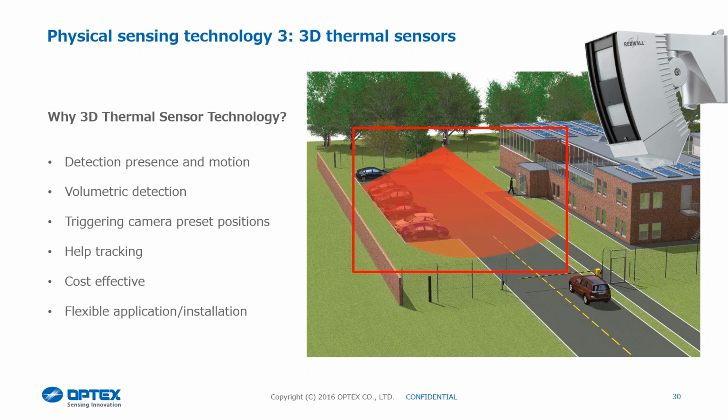Volumetric detection patterns are available, so we can go 50 meter by 30 meter, we can go 30-20, using the different presets on those, or the different outputs on those to track presets. So when we look at the 100 meter detector looking along a fence line, for example, we can give you a preset which is up to 5 meters. We can then give you another one which is 5 meter up to 50 meters, and then a third one which is 50 meters up to 100 meters. So it works really, really nicely with trigger and PTZ cameras to track somebody as they're moving around the site.